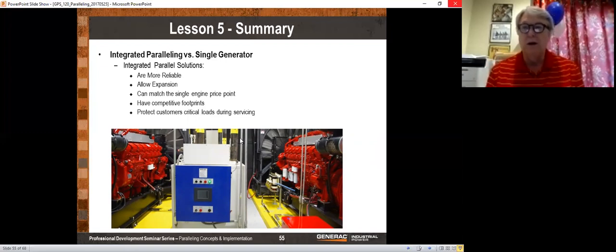In a parallel system, the load is always going to change a little bit too, but all those generators are dialed in so that, although they're going up and down a little bit with the load in the power plant, they're going to be really close in terms of the paralleling. So a similarly sized generator with a similarly sized load should pull approximately the same amount of fuel.